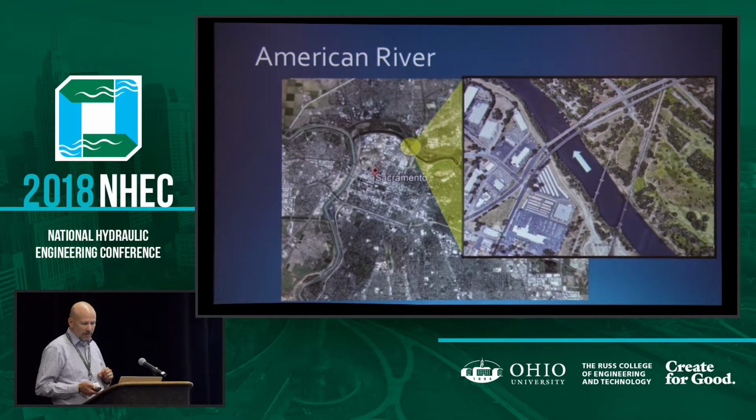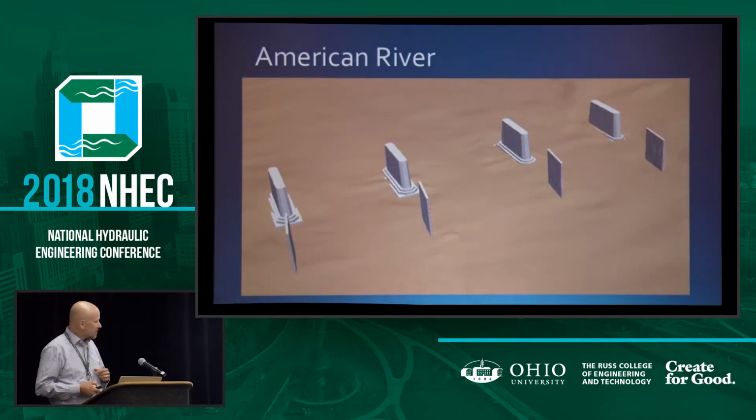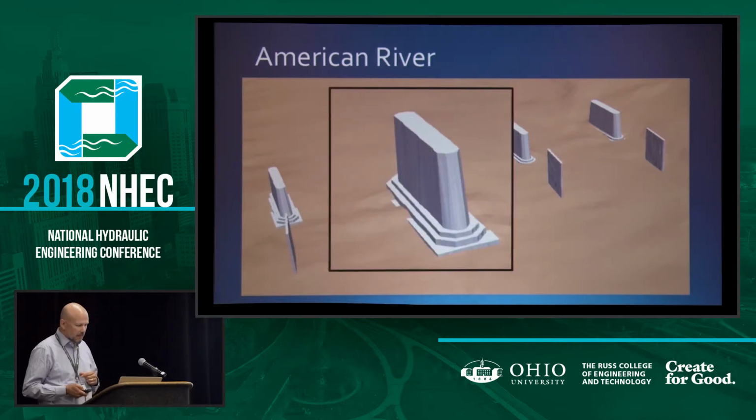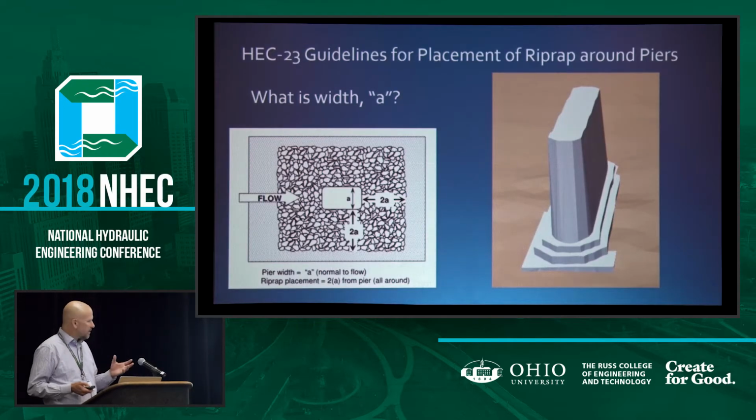American River has 4 bridges in it, and the most downstream bridge is the one of interest, which is the one here, the larger of the piers. The reason they're interesting to me was their shape. First off, the pier widths are not constant. Secondly, this strange foundation or pile cap that's stepped, and so it came down to, well, this is a scour critical bridge. There was a proposal to put rock.